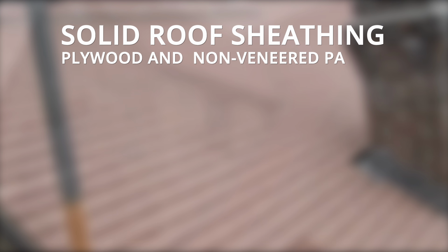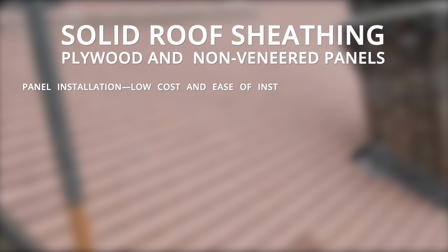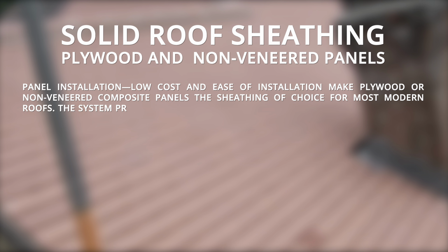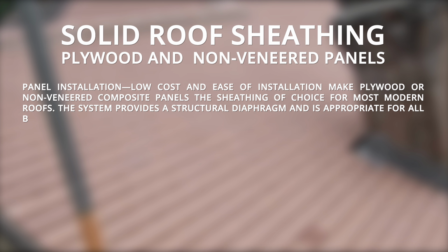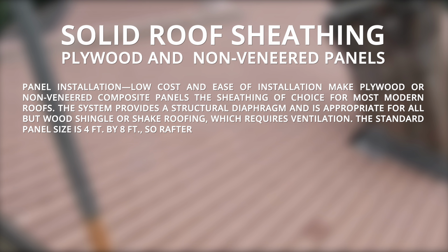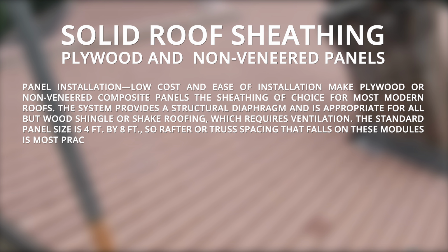Solid roof sheathing. Plywood and non-veneered panels. Panel installation. Low cost and ease of installation make plywood and non-veneered composite panels the sheathing of choice for most modern roofs. The system provides a structural diaphragm and is appropriate for all but wood shingle and shake roofing, which requires ventilation.